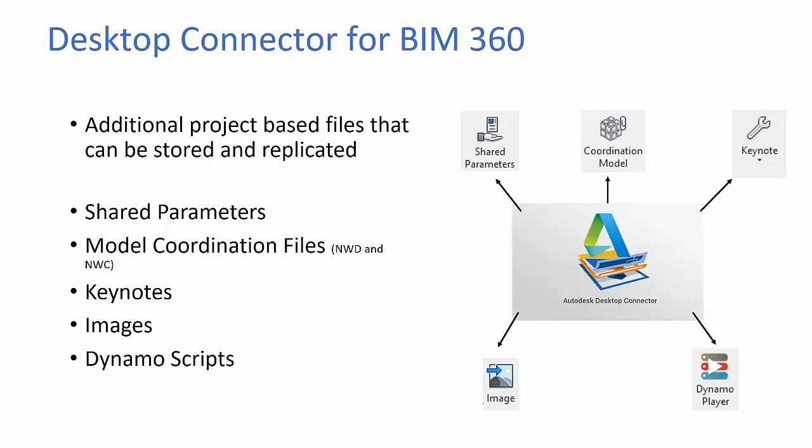Additional project-based files. So you may want to be sharing shared parameters, an NWC for model coordination, Keynote text files, a Dynamo script for the new Dynamo player that we've had inside of Revit, or an image, a graphic for a texture or a decal. All of this can be located in the desktop connector, and all the collaborators can share or reuse this non-Revit file format data.